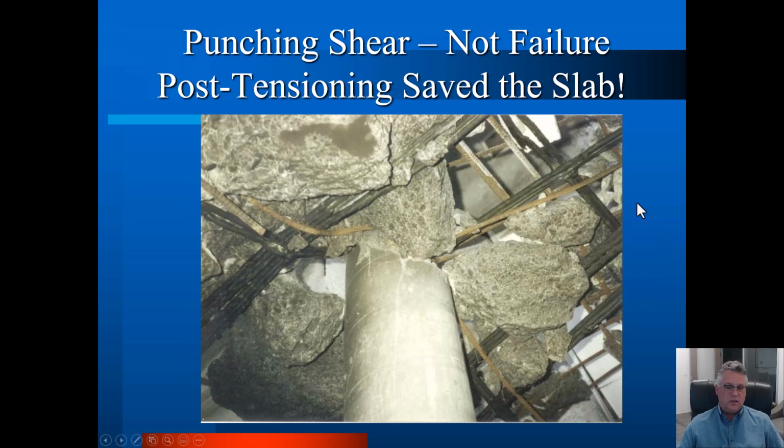So this is, and yes, my father and I walked below this building on the verge of collapse. One of us took this picture. We both had cameras, so we both took pictures of this. We both debate who took this one. But you can see those 2 tendons coming below that are hanging up over the column and then coming back down. And in the other direction, there are those 2 other ones. But that's it. That is entirely what is holding up the building at this point.